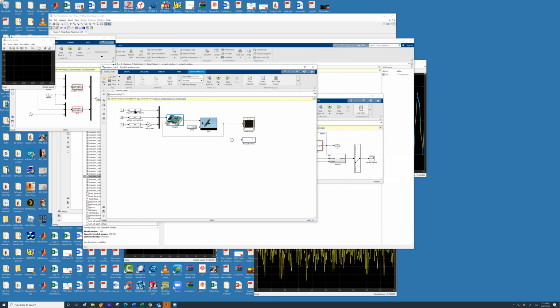And what you have here is the commanded airspeed, commanded altitude, and commanded course heading. You specify these values. Autopilot converts those into appropriate commands: the elevator deflection, the rudder deflection, and aileron deflection and thrust, sends that to MAV dynamics, and then MAV dynamics sends out to the draw aircraft.